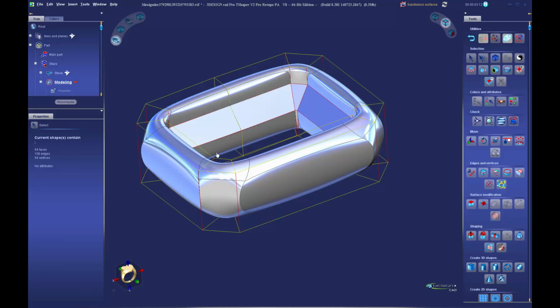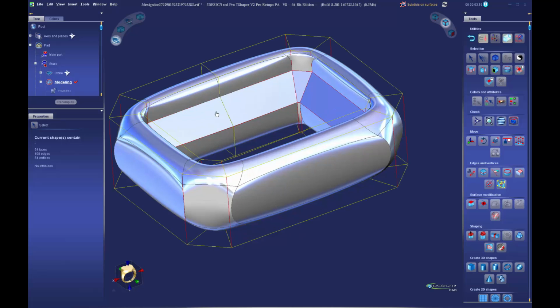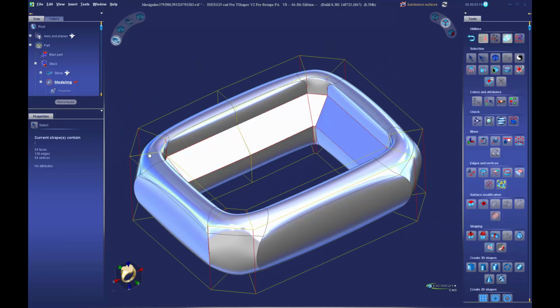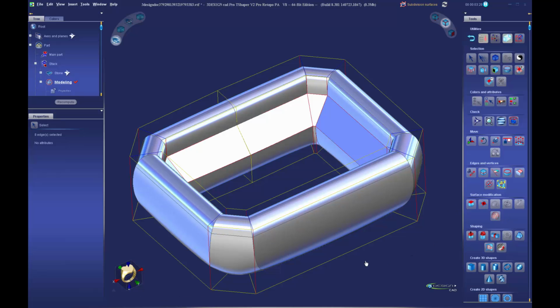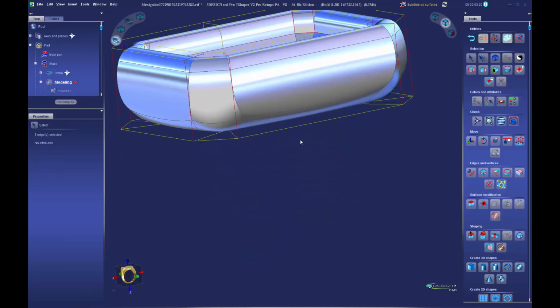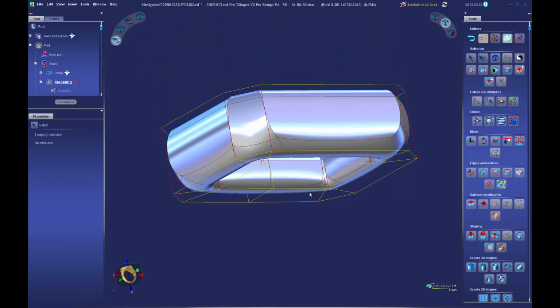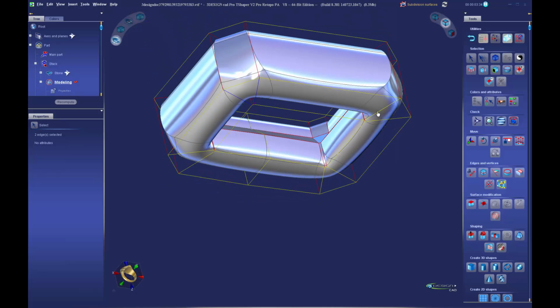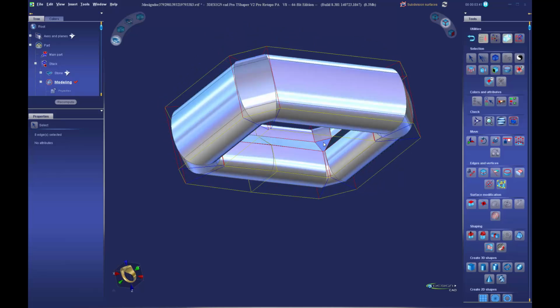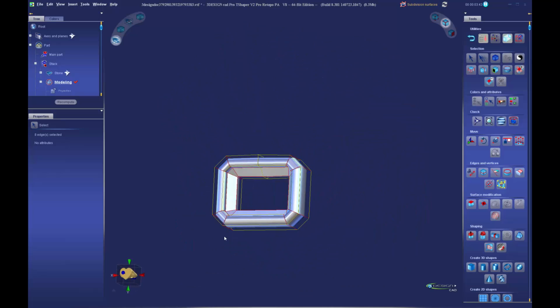Now because this emerald shape has these corners, we probably want to keep those corners sharp. So go ahead and select the 2 angled edges here at each corner. So there should be 8 of them. And sharpen those by clicking the sharp button again. And we'll do the same thing on the underside of the model. Those 2, those 2, those, and those. So 2 on each corner. And sharpen those. That'll keep our nice emerald shaped bezel.